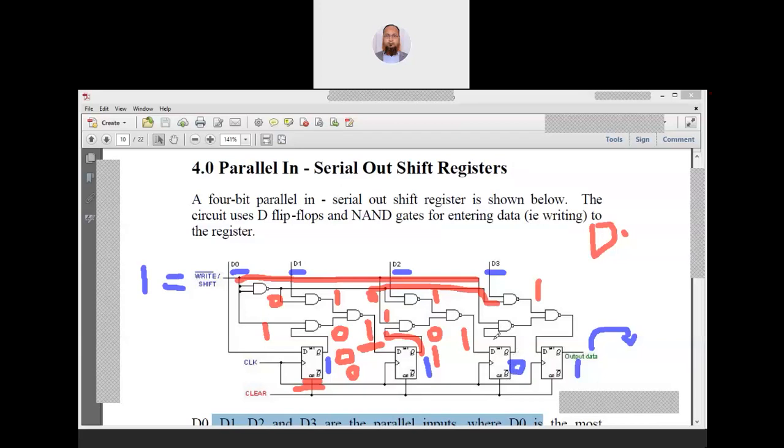Again, here what it was, 0. So 0 here, 0 here, and 1 is coming from here. So the output will be 1 here. 1, 1, the output will be 0. Okay, and as soon as the clock comes, this will change to 0. So you can see that the data is shifted to the right side, 1, 1, 0, and we can take that edge 1 directly outside. Okay, so this is how it is working.